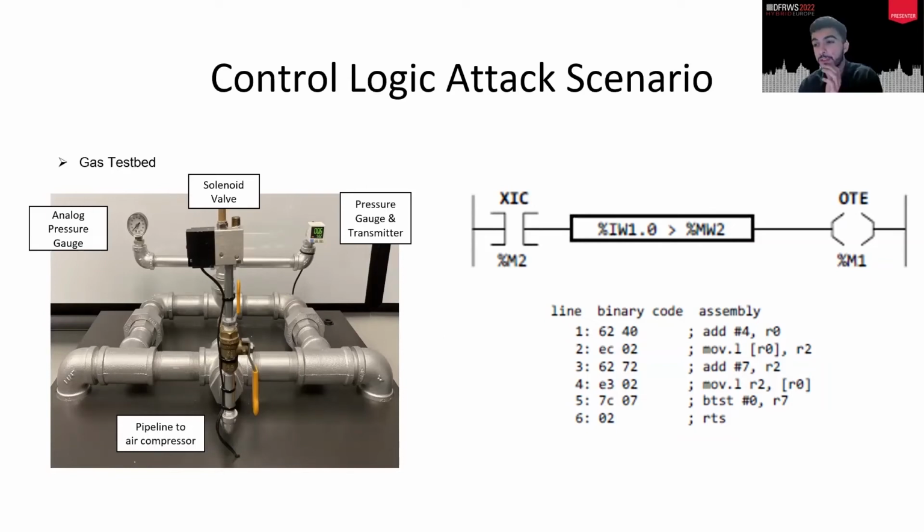And as soon as it reaches 600 kilopascals, it turns off the valves to maintain the gas pressure inside the pipelines. A pipeline can only withstand so much pressure before it bursts, so it just handles the pressure. That's what happens in industrial gas pipelines.